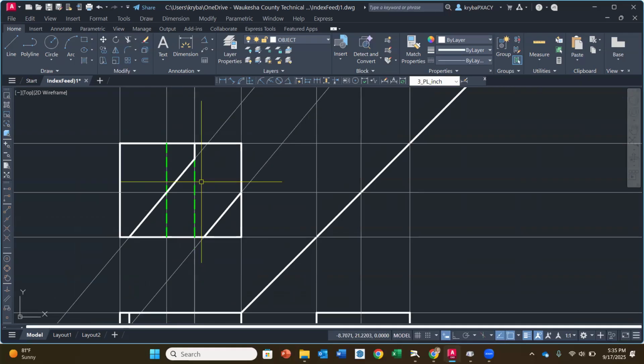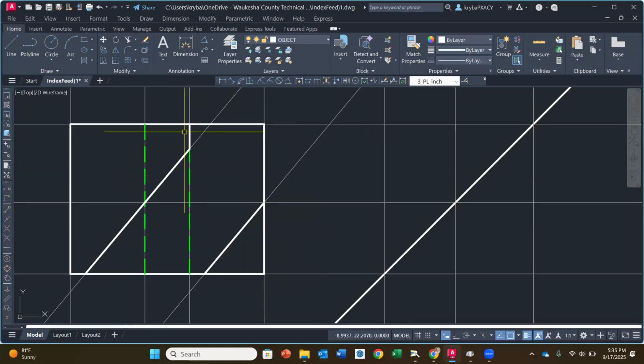If you go over the top of that hidden line, we need to deal with that. You do not want to have overlapping lines. That's not good construction. Sometimes you won't notice it. And if you hand something like this in, I may not notice it, but you know you did it. So what you want to do is, because it's underneath here, we could have trimmed it away to start, okay? But we can deal with it now. So I'm just going to left click on it, okay? And notice that it just grabs the hidden line. So don't do it on the part that the object line is over. You want to do it where just the hidden line is.